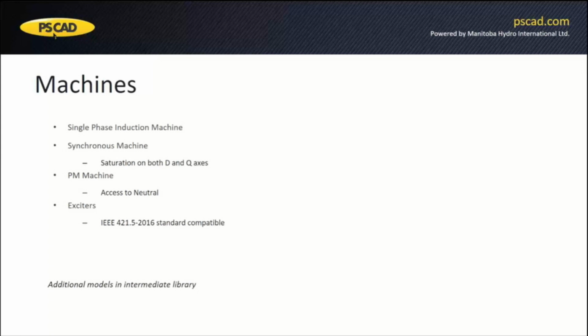Next group of components I want to show is machines. We now have a single-phase induction machine in our machines library, and we have modified the synchronous machine model so that you can have saturation on both D and Q axis. The permanent magnet machine model is modified so that you can have access to the neutral. And then we added IEEE 2016 standard compatible exciter models.